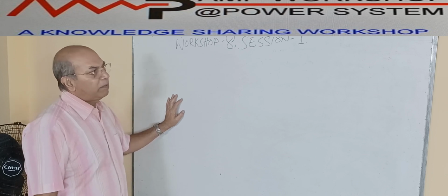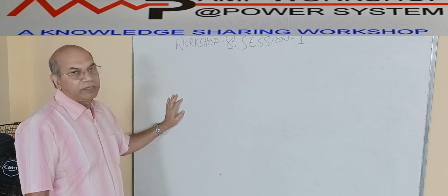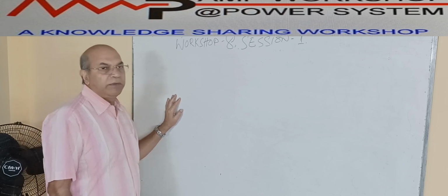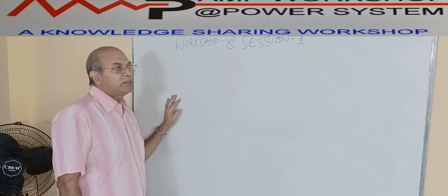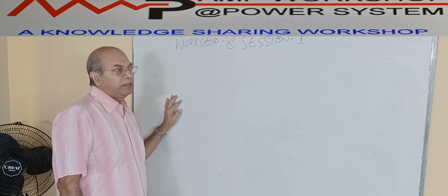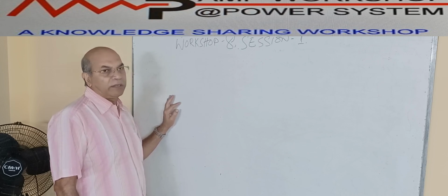And then there is another type of classification of the switchgear based on the busbar arrangements. Switchgear is again classified as single busbar, double busbar, or three busbar switchgears. But in our discussion we will try to limit the switchgears to single busbar or double busbar arrangements. Why are we discussing the switchgear in this way? Because all these arrangements have an impact on the control schematics.